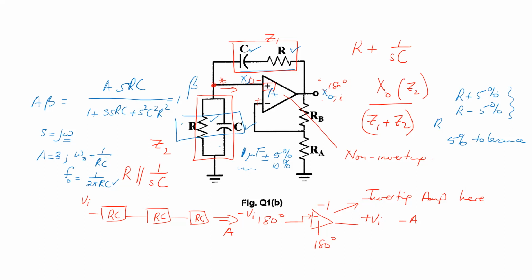So you make an educated guess. Capacitors, 1 microfarad, 10 microfarad. Remember, earlier on I'd given you all a little list that some of these components only occur in certain fixed values. So you start off with 1 microfarad and you see what R gives you here. And you use that.